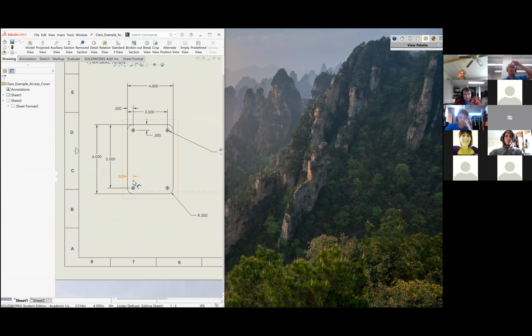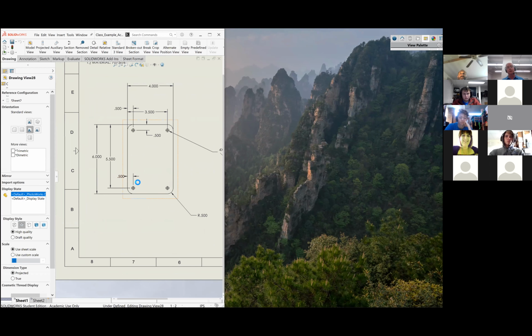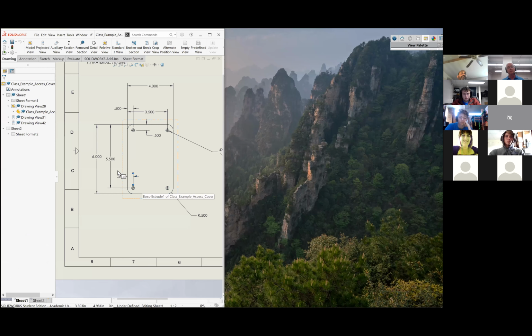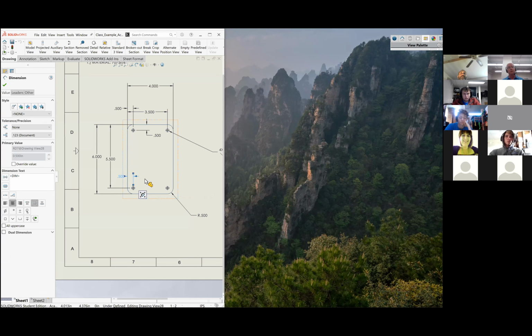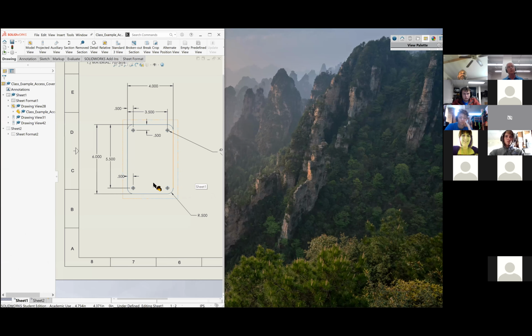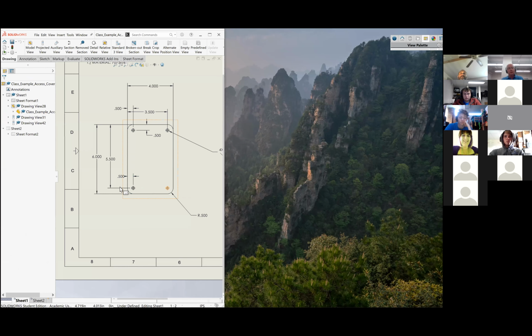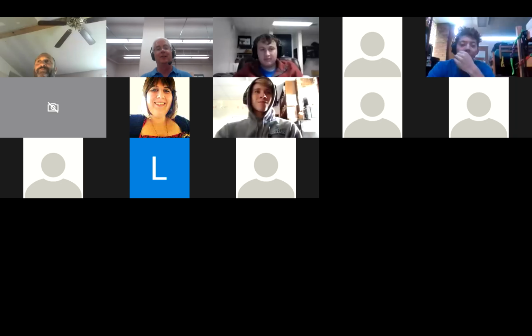Try putting a selection box around it and deleting it. Try exiting out of your smart dimension, like press escape, and then try. Nothing. Are you pressing backspace, not delete? Oh, gotcha. Yeah. Thanks for that. I'm glad somebody came up with that one because I would have never thought of that one. Thanks. No problem.